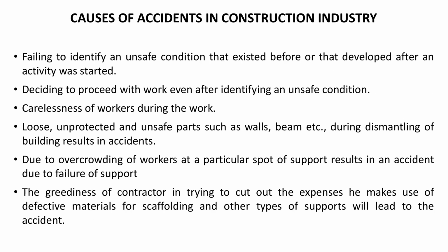Accidents in construction industry. Failing to identify an unsafe condition that existed before or that developed after an activity was started. Deciding to proceed with work even after identifying an unsafe condition. Carelessness of workers during the work. Loose, unprotected, and unsafe parts such as walls, beams, etc. during dismantling of a building result in accidents.